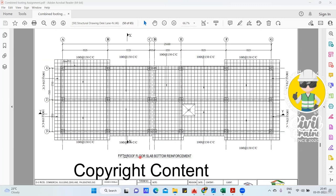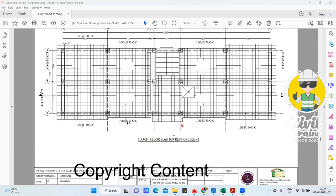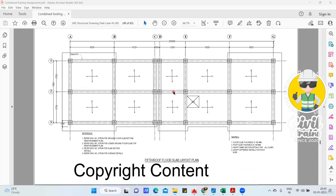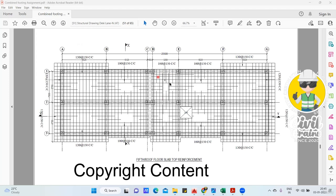Whereas if you're coming to the 4th floor, that is the open portion. This is the 4th floor, no? See, they have shown the staircase. That means there is no slab here. But here, there is no staircase shown when you come to the last floor. They have given a reinforcement because here a slab is going to come. Only that change will happen. Rest all is very simple.